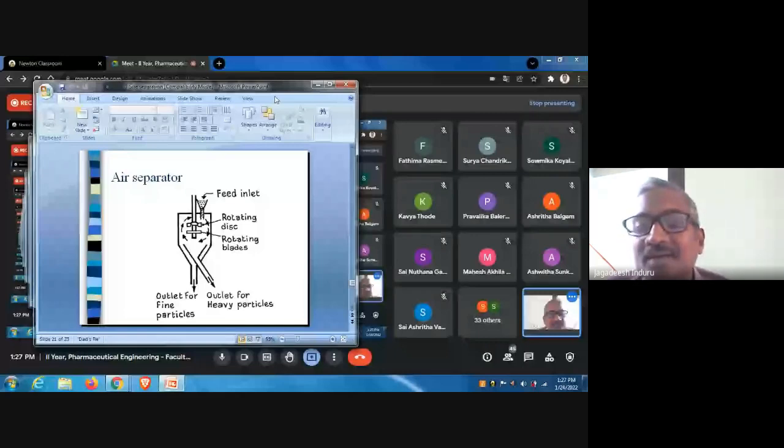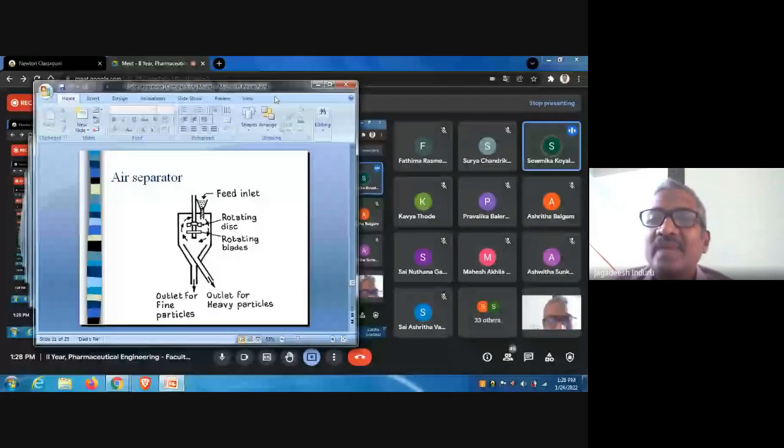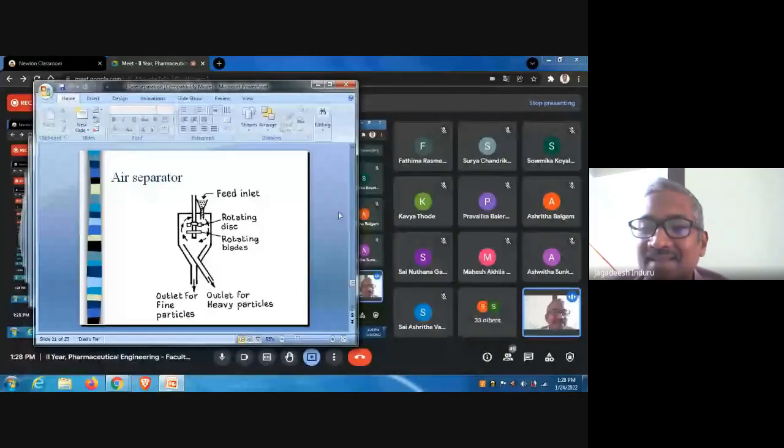You have got rice and rice flour. Which will be going to the periphery? Rice flour follows the center, rice grains go to the periphery. Yeah, because wherever they are lighter in nature, they tend to be pushed outside, and the heavy ones tend to fall at the center because of the mass, because of gravity. Gravitational force is more when the mass is more, and the material with less gravity will go along with the winds of the air created by the fan. It is going to the periphery.